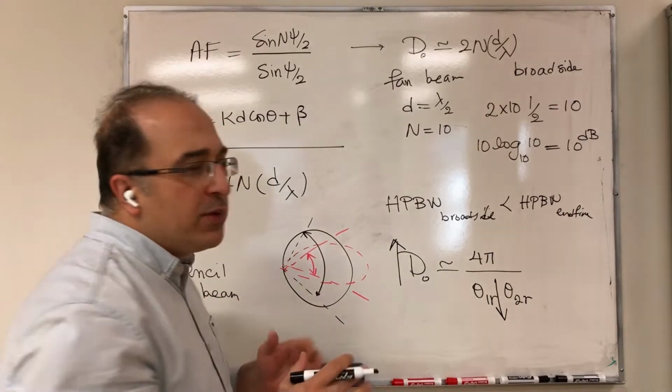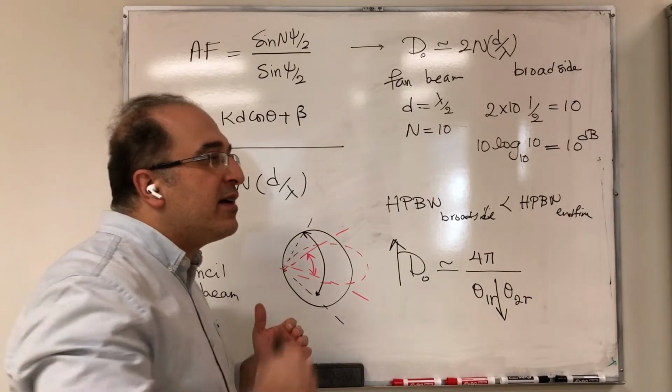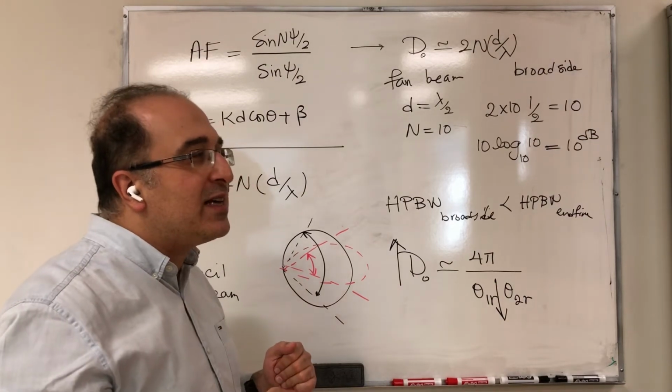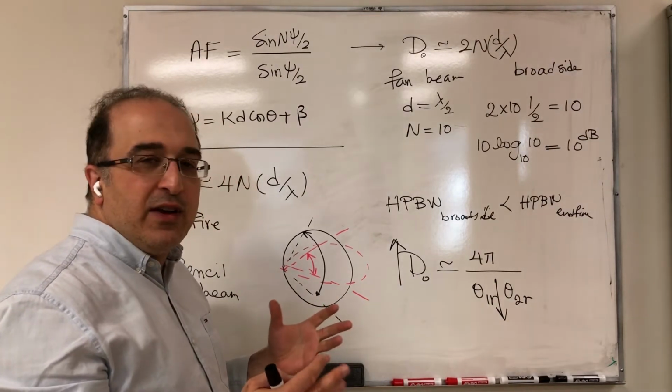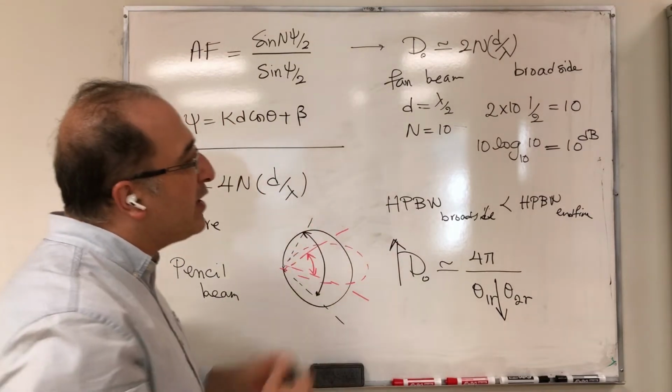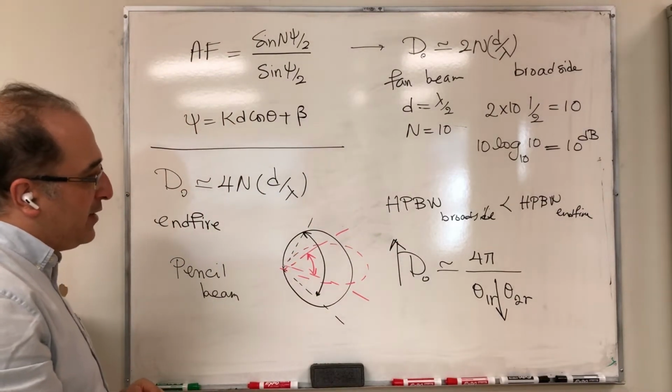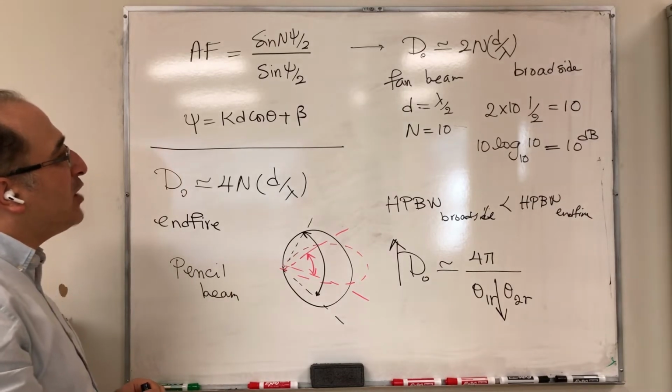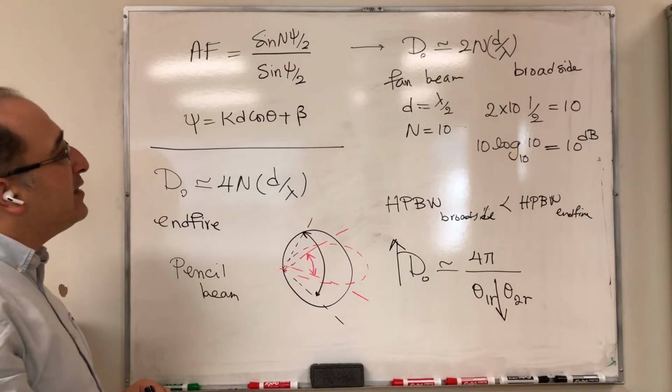Just keep this in mind, because usually as soon as we say directivity is more, half power beamwidth is less. This is very typical to say, but it applies when you are comparing the same type of antenna. So that's one discussion I wanted to have regarding the directivity.